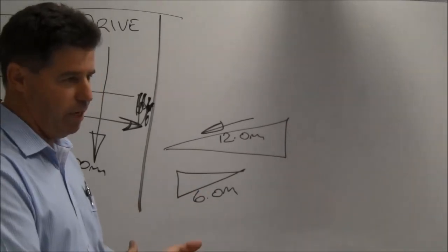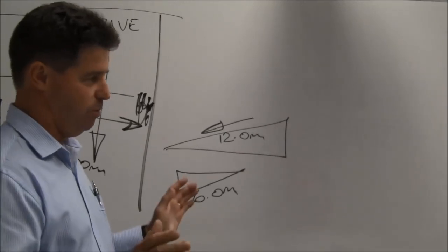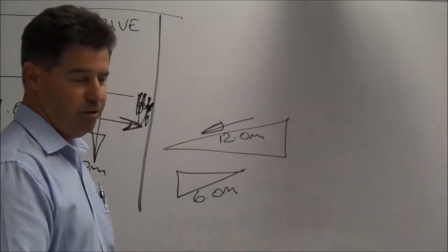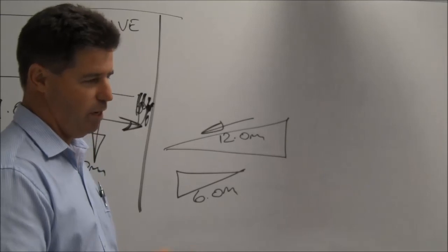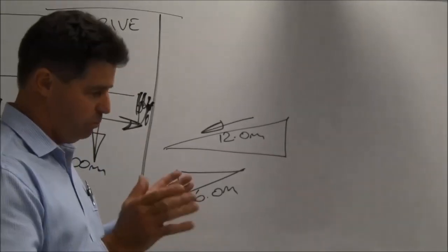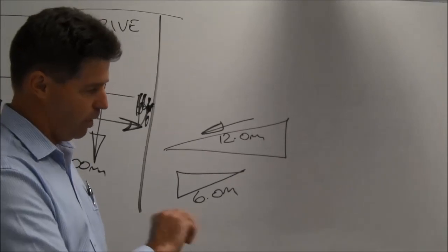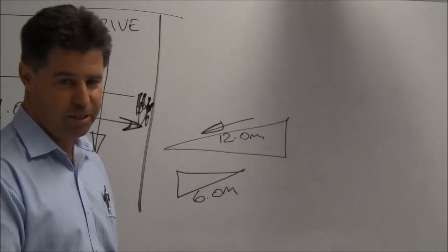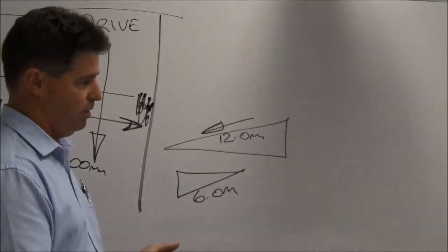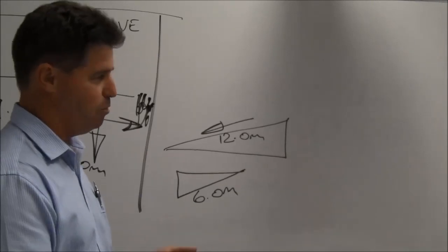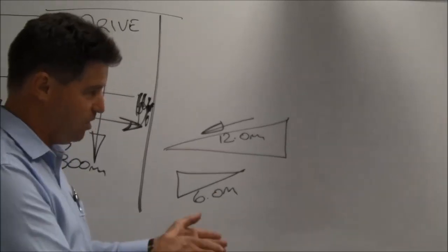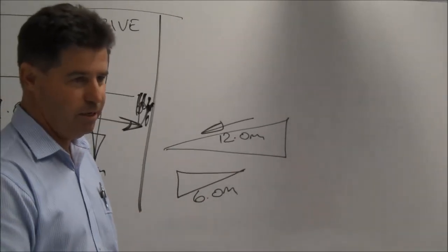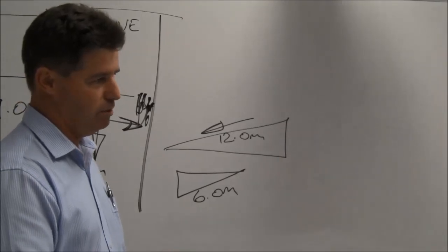In there it says that we can design to anything we want to, provided we can justify it by calculation. So we don't have to use 3500 for a sewage system, for example, and we've done it many a time with Brisbane City Council. We justify the size of our sewer by calculation. They are sometimes difficult to deal with, and we've had to get professional engineers to certify our stuff, which is fine. But once they know what you do and how you do it, we're now recognised, so we don't have to go through the whole process again. We've justified it a few times, so we're right to go.